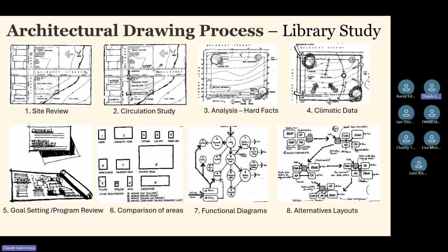This is what's called bubble diagramming, number 7. And then number 8, we start taking those larger chunks and we take a look at different alternatives. So we can see we have 4 or 5 different possibilities of how this layout could be put together into a functional diagram in which we create some suggestions of space. We talk to our clients about these things, about what do you think? Certainly we as the architectural side have our opinion, but certainly the client's point of view is always important to be considered.